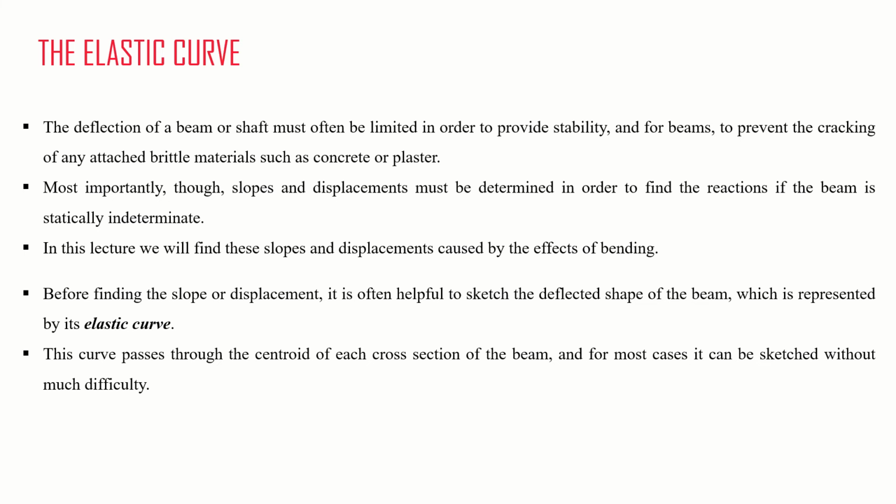Now before understanding the deflection, you need to know about the elastic curve. What is the elastic curve? As you know, the deflection of a beam or shaft must often be limited in order to provide stability, and for beams to prevent the cracking of any attached brittle material such as concrete or plaster, right? So it is very important that the deflection of the beam must be limited to overcome the instability for beams. Alright, most importantly, those slopes and displacements must be determined in order to find the reactions